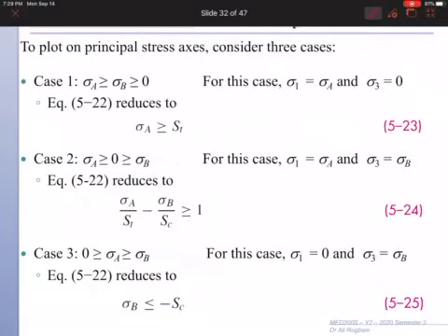For the first case, when there is no compression, you see your two principal stresses. When you calculate the two principal stresses, you get two positive values. So in case 1, there is no compression. So sigma 3, or smallest sigma, is 0. There is no need to compare your compression stress with compression strength, because there's no compression stress. So only use sigma A with this formula.